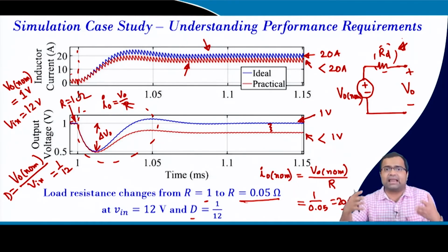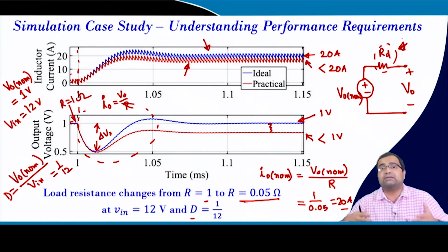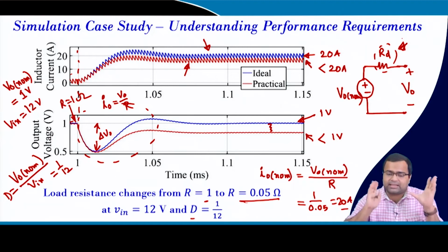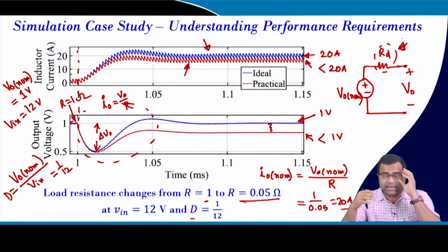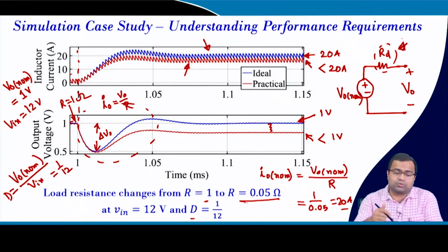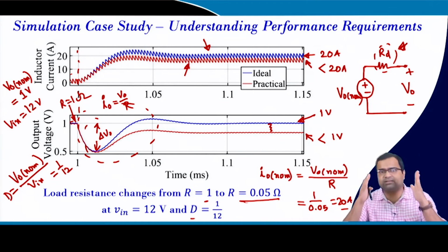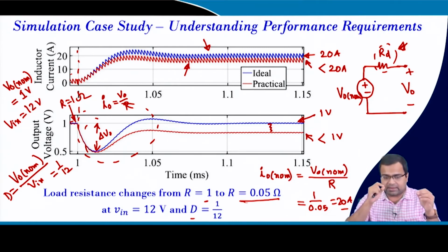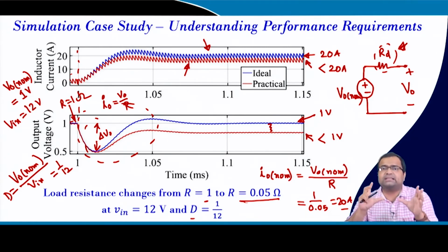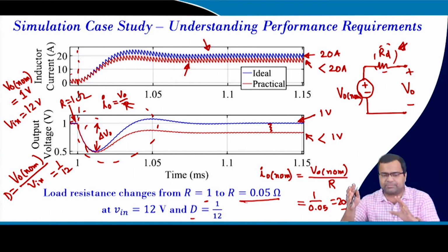We need an integral action to reach zero steady state error, but that may take some time. Another thing we will see, the need for control is that this undershoot is not acceptable, because in the very first lecture we said that in processor applications our current repeatedly changes, like a large step transient happens, step up, step down.